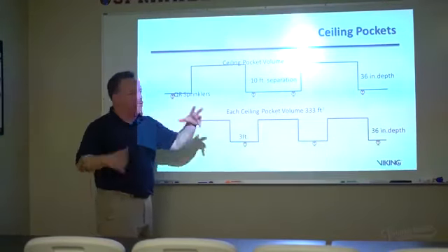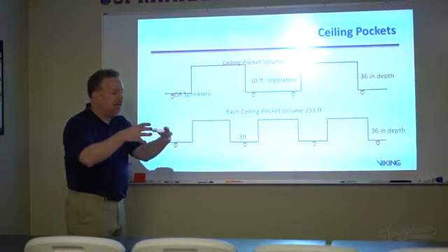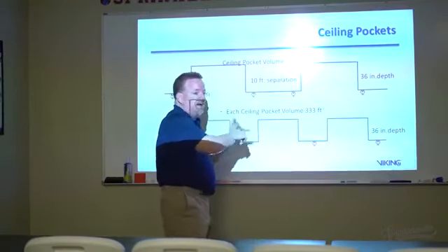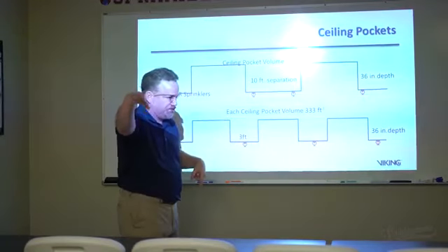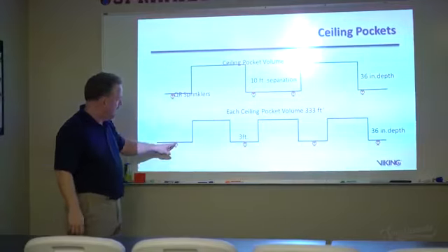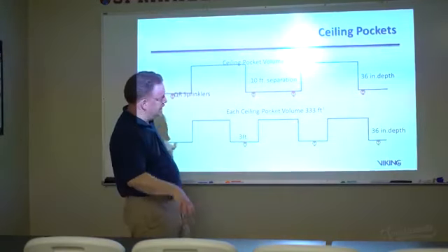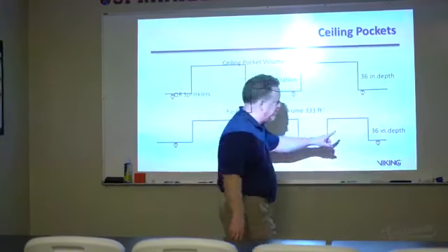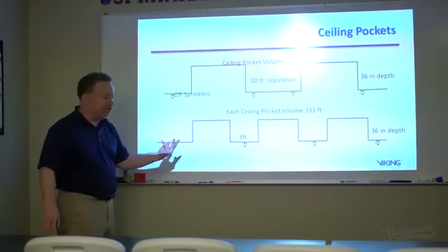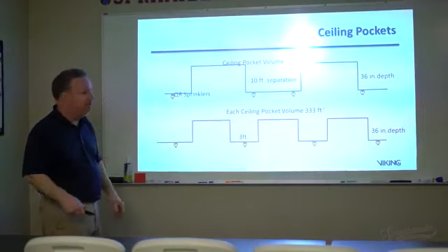The accumulation of those three in one area is permitted, as long as this whole accumulation of 3 is now 10 feet from the next accumulation of 3. And you have to have a sprinkler head at each down projection? Well, you have to have your spacing. Right. Correct. Now, just for showing it, we put sprinklers at each one, but you might not need to do that.